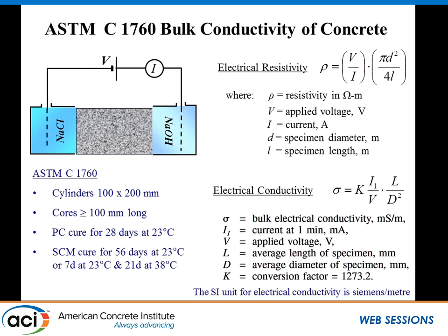Many of you probably know that ASTM has, of course, had a kind of resistivity or conductivity test on the books for a long time. It's known fondly as the rapid chloride permeability test. Whatever we like to call it, even though we use the words chloride permeability in its name, it is in fact just an electrical conductivity test. Quite simply, that's all you're measuring with that test. You just take 5 hours and 59 minutes longer than you actually need to. It's a very long-term electrical conductivity test.